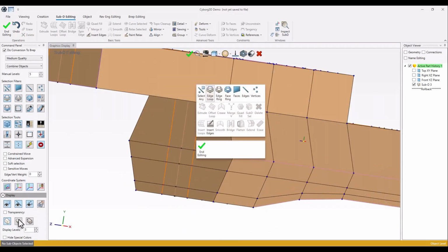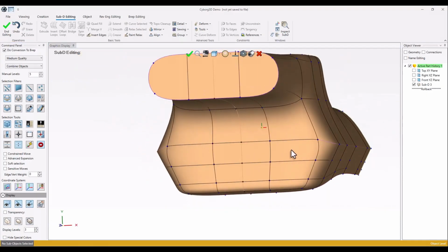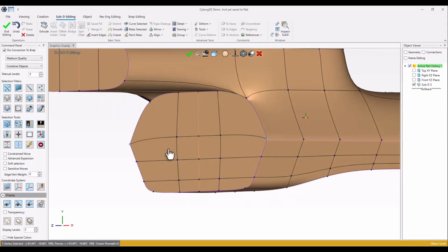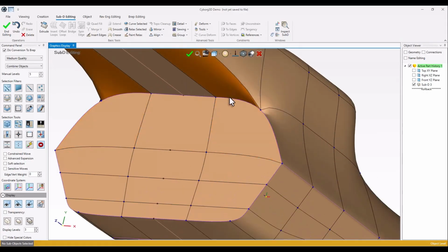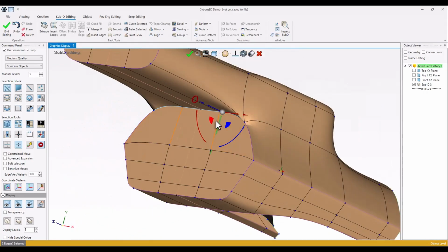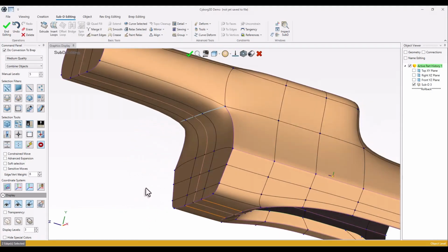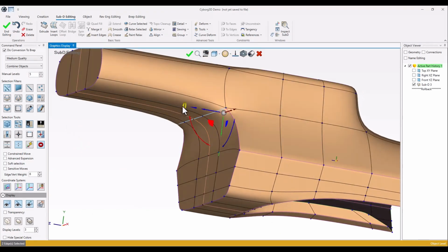Now let's just go to subdivision mode for a second, and you're gonna see I need to crease these full faces. So selecting them all, I can right click, use crease. So now it's just fully creased. However, I might use a little bit less creasing here, so it gives me a good fade or good transitioning between them.